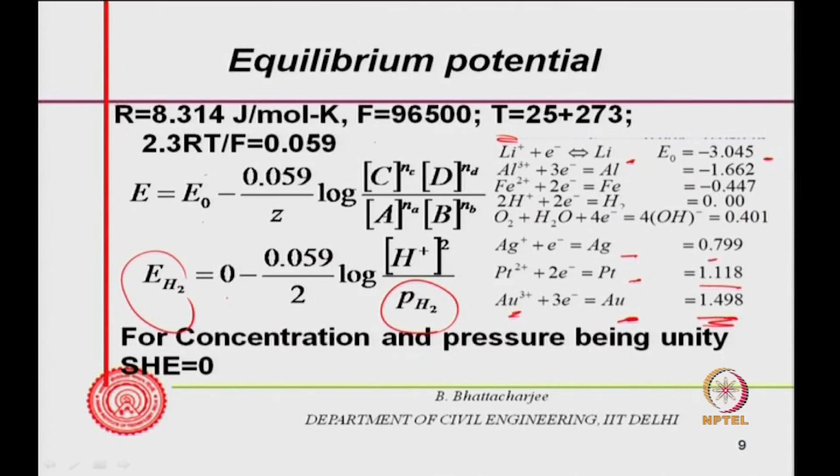So, noble metals have positive electrode potential, they do not form an anode. The dissolution reaction does not take place there readily, while in the case of other ions such as Fe, this reaction would occur, it would act as an anode. So, you connect Fe with gold, Fe will automatically become anode and gold will be cathode.